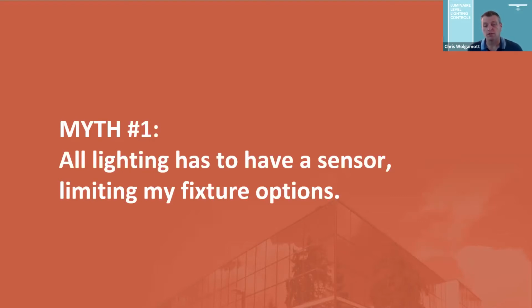And almost all the systems that are luminaire level have the capability of doing both. They have the integrated sensors for the general lighting fixtures, and then they have the standalone sensors that can work multiple fixtures at one time. And so I think that's the thing that is out there right now, that in reality it is a very combo system, but what we're wanting is the majority of the fixtures in that general space to have a sensor in every fixture to give that granularity and that view of the space to control the fixtures better.